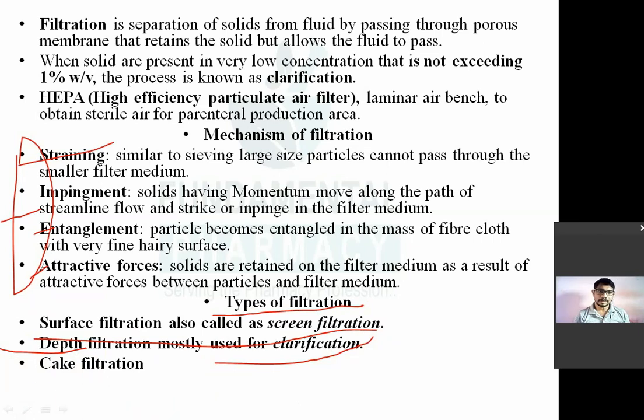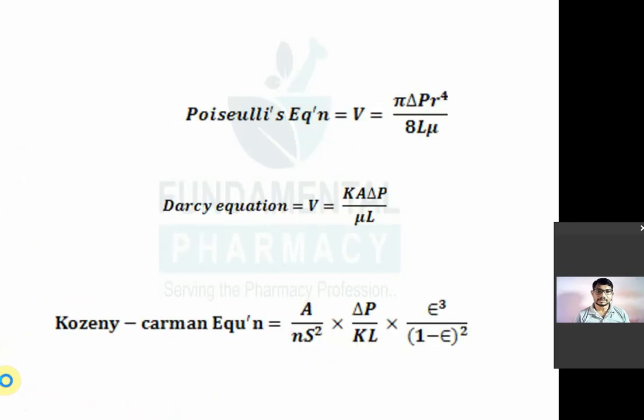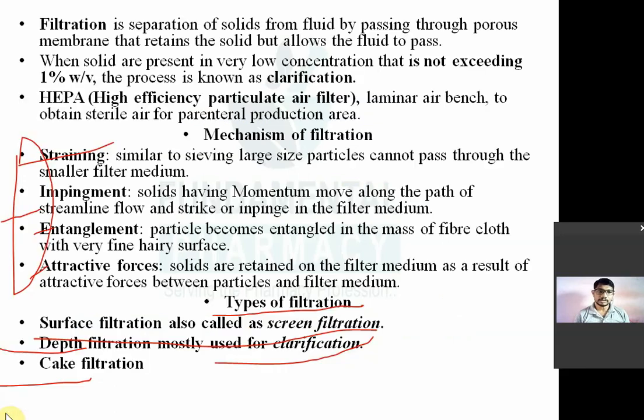And I have told you what we mean by clarification. When the solid content of your slurry or fluid is less than 1%, instead of using the term filtration, you have to use clarification. There are two types of filtration I have told you: first one is surface filtration or screen filtration, and second one is depth filtration.